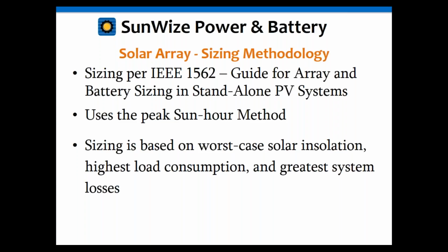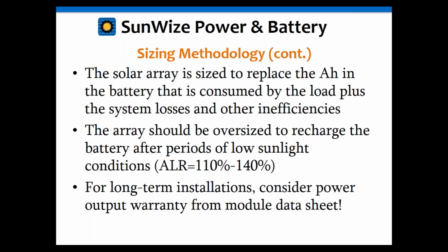And always, of course, take into account the greatest losses and the highest load consumption. Again, we're always trying to be conservative. We'd rather have a system slightly oversized than to have it undersized and not work or fail prematurely.